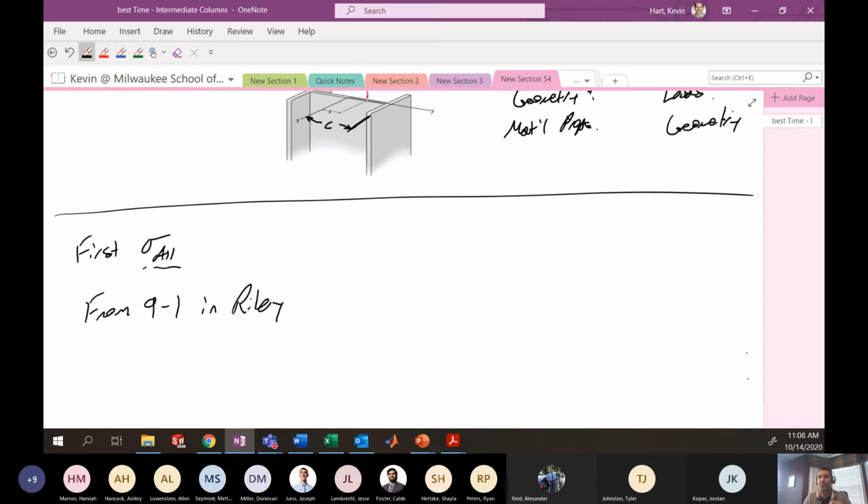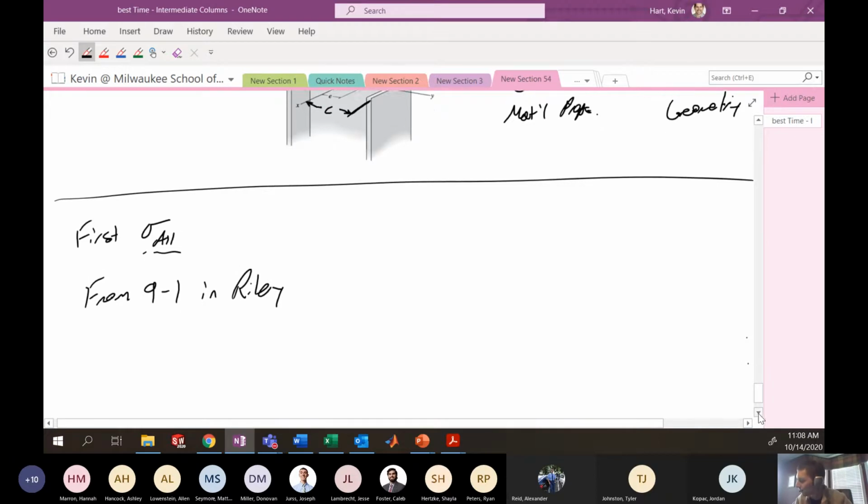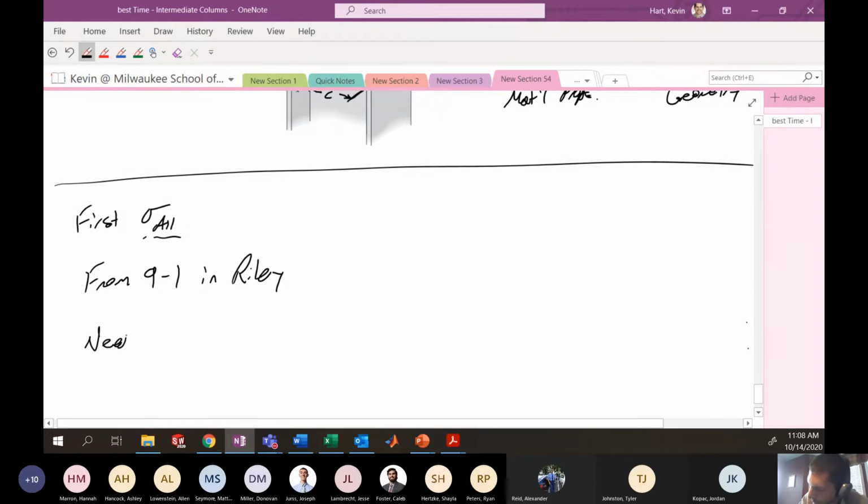All right, so if we're trying to determine the allowable stress, we need to determine whether we're in the compressive range for very short columns, the intermediate range for an intermediate column, or the slender range for very long columns. To do that, we first have to determine the slenderness ratio, and then compare what range we're in based on table 9-1. To determine the slenderness ratio, we need to know about which axis we're going to buckle.